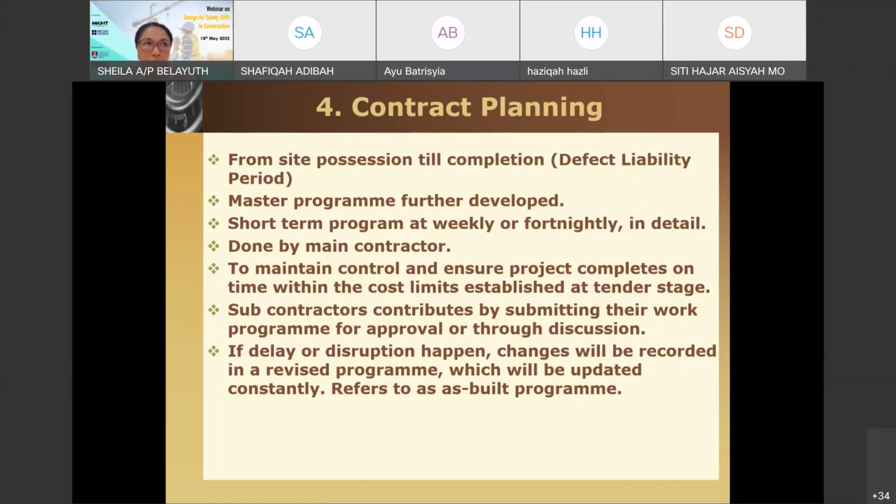If we don't provide as-built, for example, let's say for a construction site we have a TNB cable running under our site, and we need to divert it, and it was not given in the consultant's drawing. According to the drawing, we should run above the TNB cable, but on the site we realize that there is such a cable. So we can't just run over it, and we need to divert so that we do not encounter the TNB cable. Hence, if we don't have the as-built, the client would not know where we actually diverted our structure.